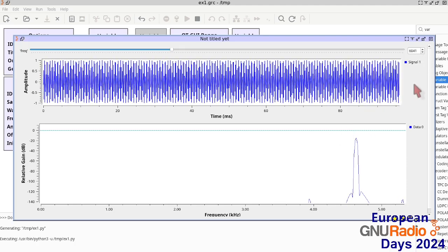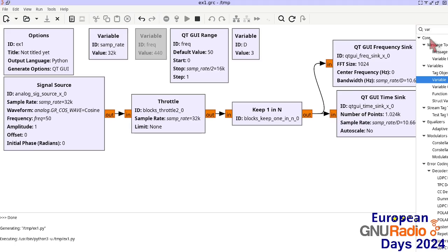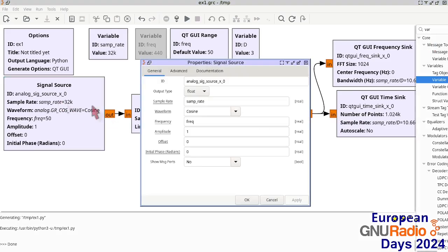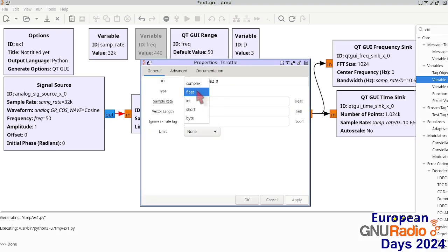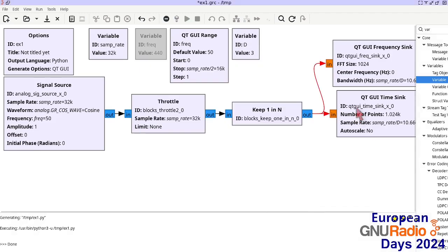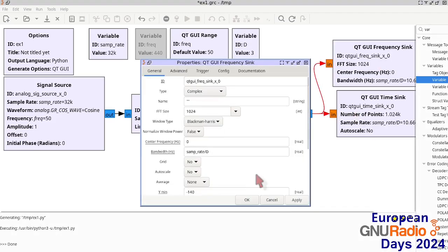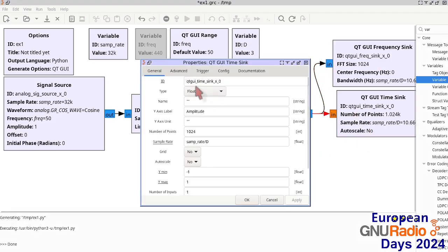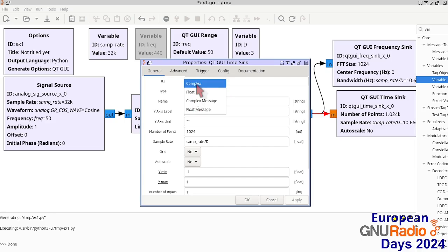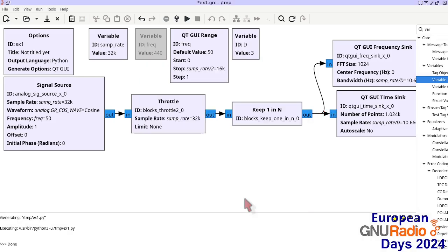Let's see with an imaginary quantity what is actually really happening. So if we now change all our real quantities to complex numbers, so actually we just switch all the blocks back to the complex default behavior, now we see that the spectrum is a full spectrum because there is no reason for the spectrum to be even once we've reached complex quantities.